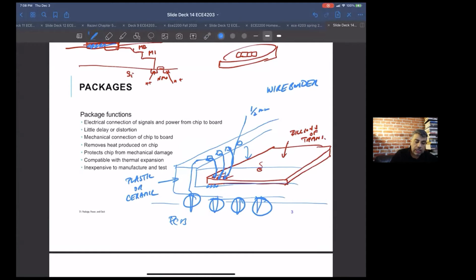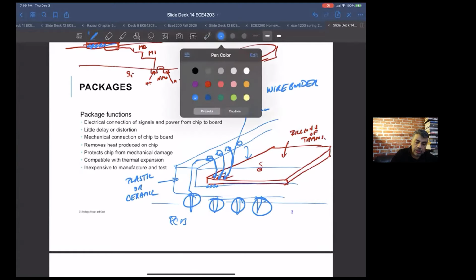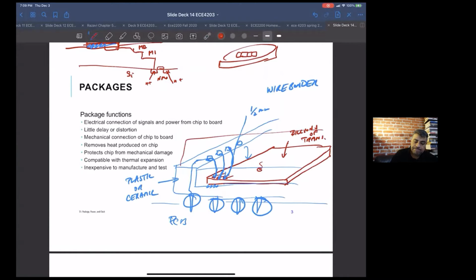After you're done connecting all up, what you do is you seal this thing. So, if you look at like, I don't know, an Intel microprocessor or something, or a Xilinx FPGA, you won't see the chip in the package. Maybe the chip package is that big because it's sealed. They put sort of epoxy on top of the whole thing, so it's protecting it against scratches, protecting it against humidity, any kind of other stuff. So it's also protecting the part.